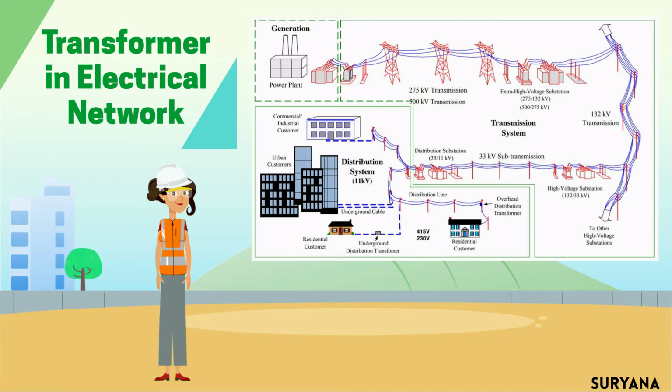Distribution feeder circuits usually consist of overhead and underground circuits in a mix of branching laterals from the station to the various customers. The circuit is designed by considering the required peak load, voltage, distance to customer, and other local conditions such as terrain, visual regulations, or customer requirements. In distribution, there are two types of systems that are used, that is overhead lines and underground cables. High density urban areas are often connected in a complex underground distribution network, providing a highly redundant and reliable means of connecting to customers.